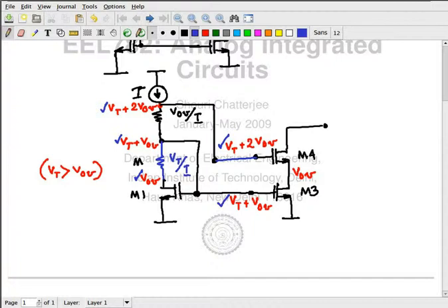Where are you coming up with these numbers? What I wanted to say is that the value of Vt changes with temperature, from technology to technology, from device to device. Even if you change the length, the value of Vt is different. Okay? So basically Vt is something which is very, very unpredictable. You shouldn't build resistors based on Vt.